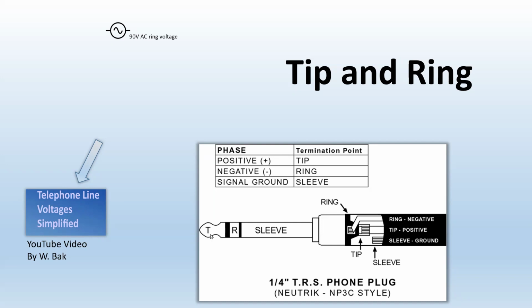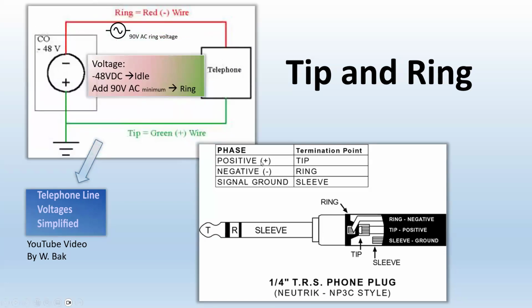So because a telephone line is just one pair, which is one wire and the other wire, and usually they're twisted, right? Remember? So we just use tip and ring. Some jacks have tip and ring and sleeve. Some jacks have just tip and ring. And in audio, some of those are being used for stereo versus mono signal, or balanced versus unbalanced signal. And this is also something we're going to cover in a little bit greater detail today, before the cows come home. That's what tip and ring looks like.